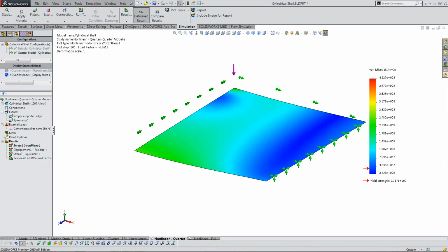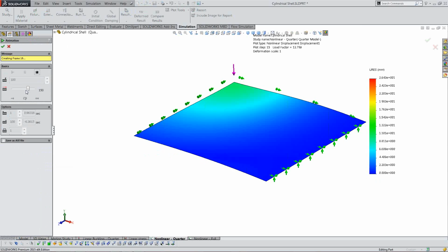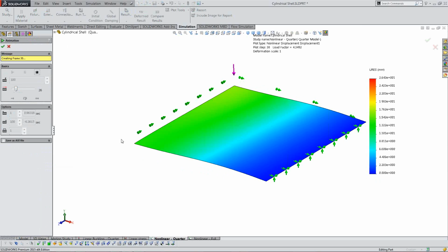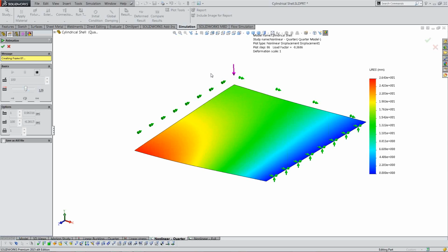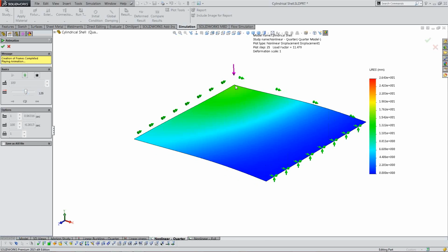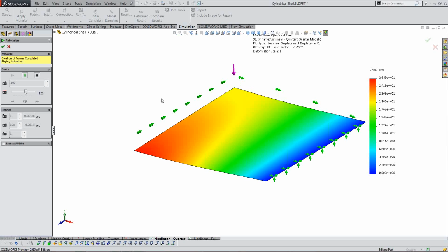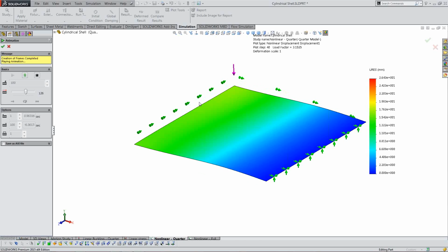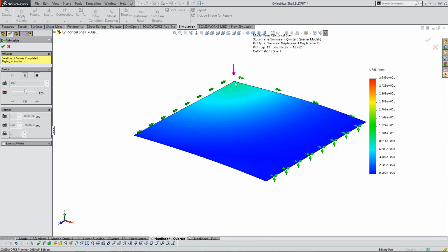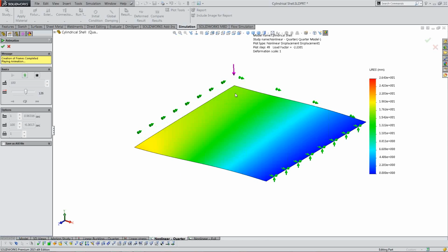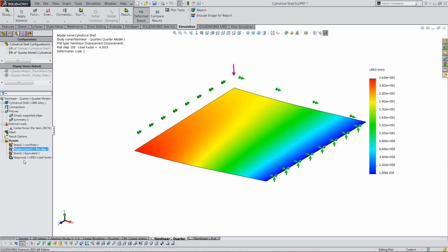We can actually animate this. Let's look at the displacement plot. Slow this down a little bit. Keeping that graph in mind, what we see here is the initial buckling, and then the secondary buckling is this outside arched edge of the sheet. So we're pushing down, and then the secondary is this, and then the snap-through occurs, and then the force would continue to build because it's now in a stable, inverted configuration. So the linear buckling tool was pretty far off on this prediction.